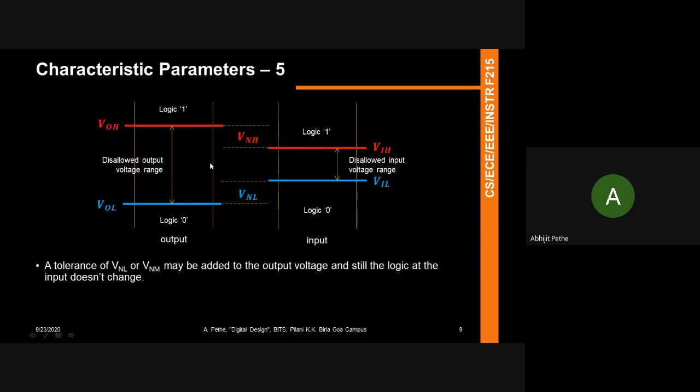Harsh, what is the difference between supply current being high or low? Is there no output when it's low? That is the thing I want you to understand. Just because the node is low doesn't mean that the node has 0 volts. A node can have some voltage. Whenever you say high and low in digital electronics, it is normally associated with both the voltage and the current.